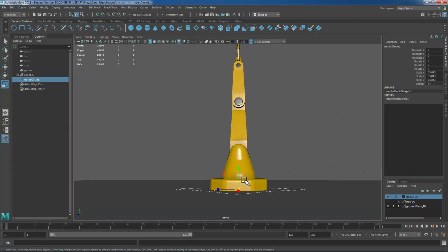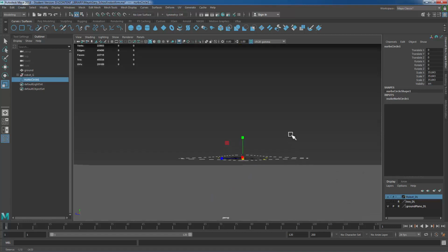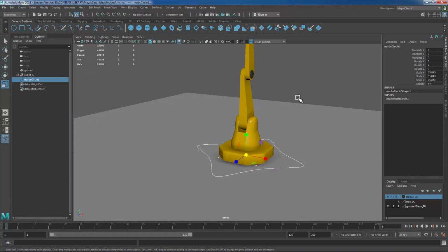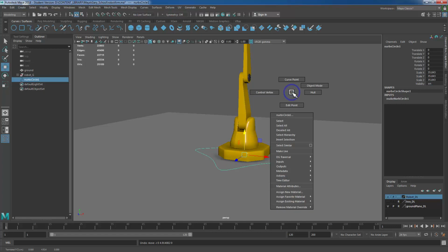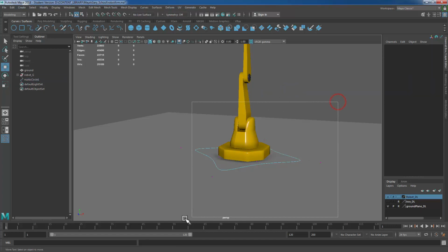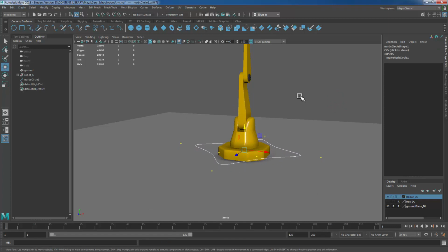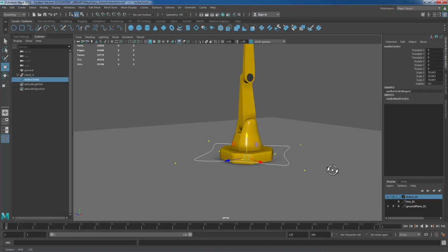I would like this handle's pivot to stay at the ground where the object's pivot location is. But it would also be nice if the handle shape was not on the ground. And I can do this two different ways. I could just object select the handle, move it up where I would like it, and then move the pivot back down. But the pivot currently is exactly where I need it. So if I translate this by using the control verts instead, if I select all of them, these can be moved, put this someplace selectable, but the object's pivot location has still stayed at the ground value.